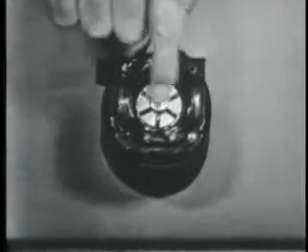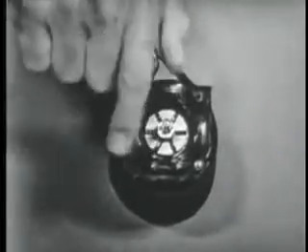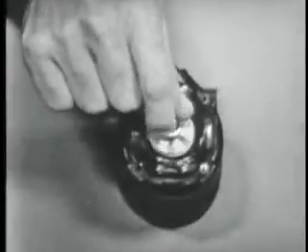In the induction motor, the moving or rotating magnetic field is supplied by the stator field windings. The rotor follows this field movement because it becomes an electromagnet. In other words, when current is applied properly to these windings, a magnetic field is generated that rotates about the housing. Now, the field windings do not move themselves, and this rotor is not a permanent magnet.